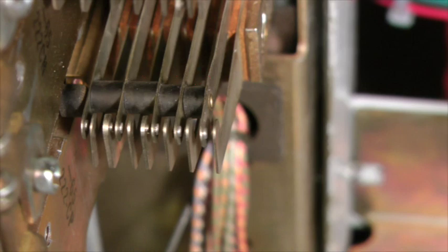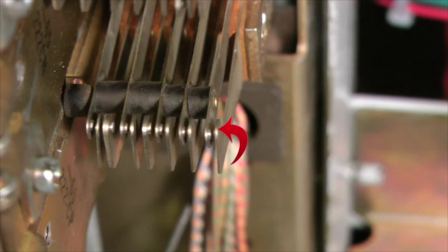Operated contacts 1 and 2 complete an energizing path to the F relay's secondary winding. The much higher flux through the secondary winding, which has over twice as many turns as the primary winding and a slightly higher operating current, allows the F relay to fully operate. The F relay is held operated via its secondary winding for the duration of the call.